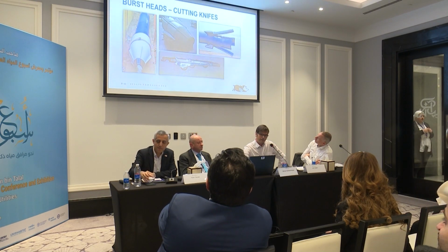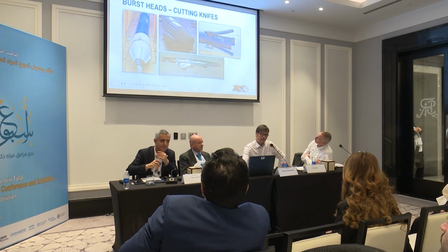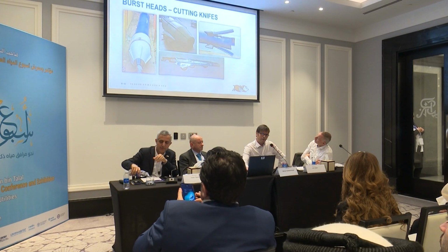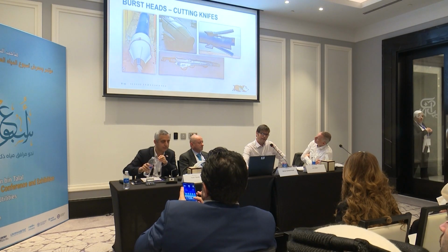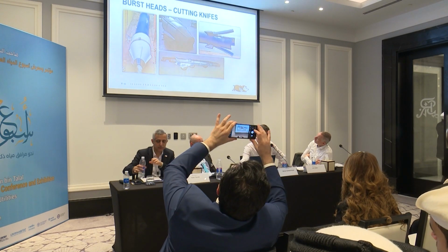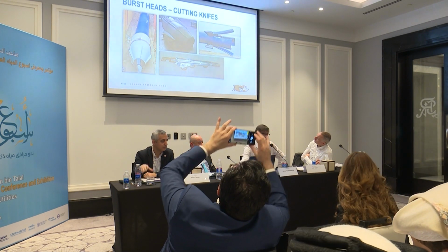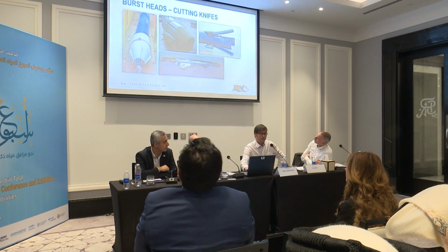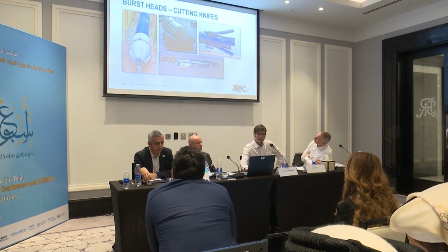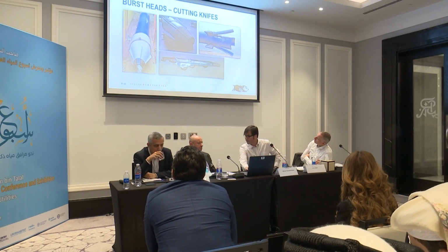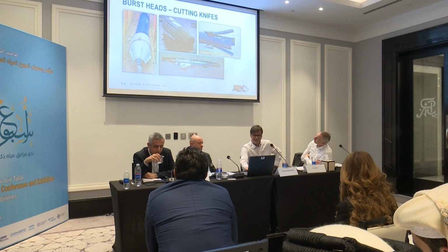So for every material there's a different bursting head, a different expander. This is a four-fly cutter to burst PE pipe, because believe it or not, PE pipe is already being burst because they've come to the end of their life cycle, probably through poor installation. I agree with you there.